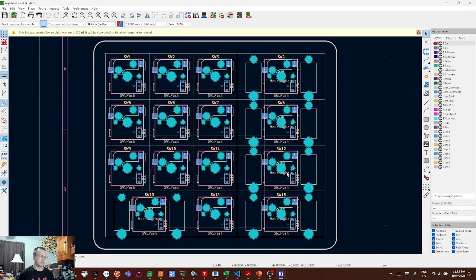Alright, what are we looking at here? Well, obviously we've got the outline of a printed circuit board, and we've got outlines for a whole bunch of components. We have shapes approximating key caps, the key switches themselves. We got some light blue holes here for the hot swap sockets and the key switch itself. And we've got diodes placed down, which will be an important part of our keyboard matrix that we'll talk about in a minute. All of the objects shown here are in a specific layer, and we're going to turn some of them off so it's not quite so cluttered.